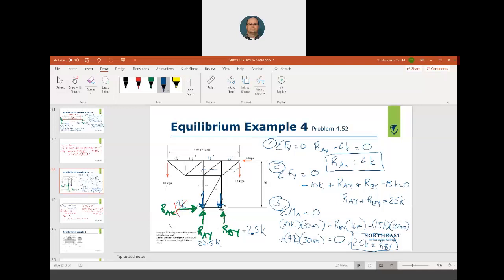Okay, and then there's a horizontal force that the shafts have to hold to resist the horizontal load, because that could be a wind load. So notice what I did. I went from the reaction to the structure. My lines of action are the same, my senses are opposite, my magnitudes are the same, and the points of application are the same.